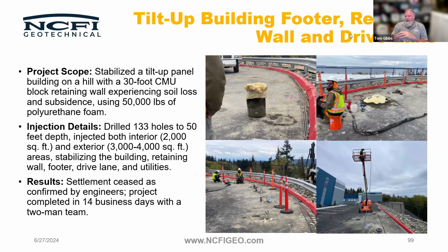If it's that soft, it can be pushed by the expansion of the foam. And you start getting into the double digits, it becomes less viable. The higher that number gets, the less likely. But also, the higher that number gets, the less need there is for it, right? At a certain point, 30 blow count material is great material. You're not going to need to improve that soil, but it does have its limitations. It's not going to be great in a 15 blow count material. It's going to be tough to get much in, but you can still do it. It's just a matter of it being a little more difficult to get as much in, and it's going to pack in a lot denser, so you're going to need a lot more material to see significant improvement.